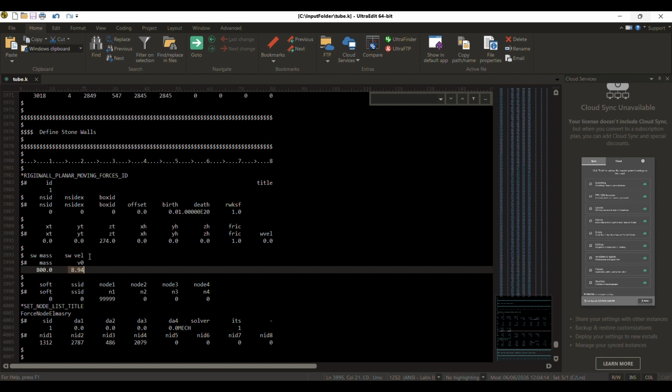The rigid wall is useful because we don't need to mesh the impactor as a separate deformable body. Instead, LS-DYNA treats this wall as a rigid moving surface. So it's a bit easier and actually faster to simulate. It's a very efficient way actually to apply impact loading, especially for beginner examples, right?